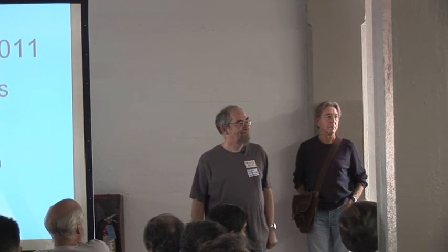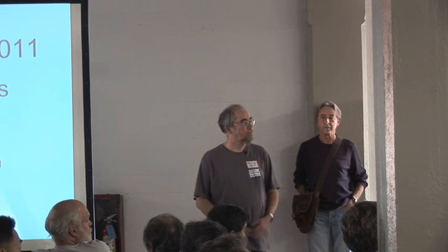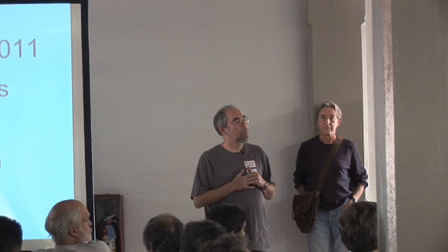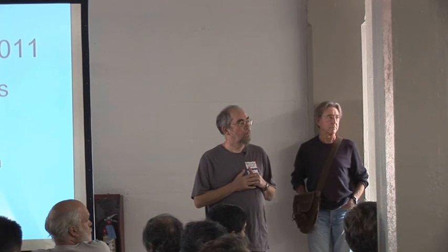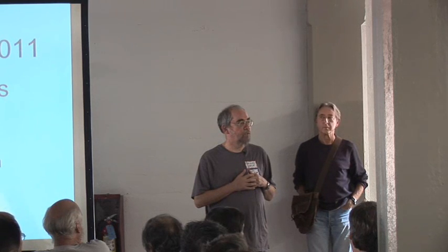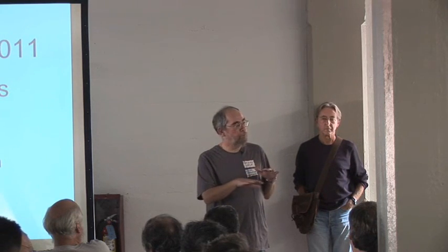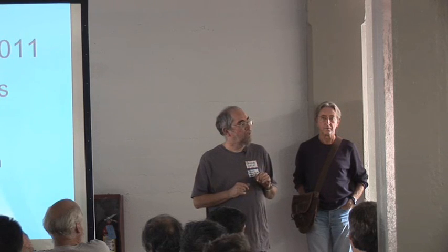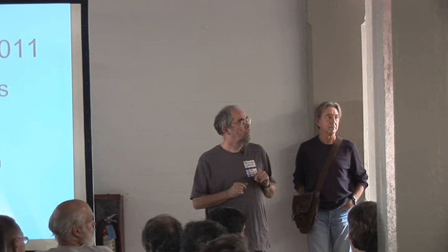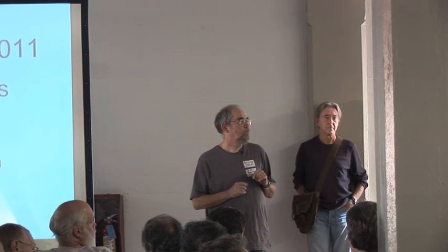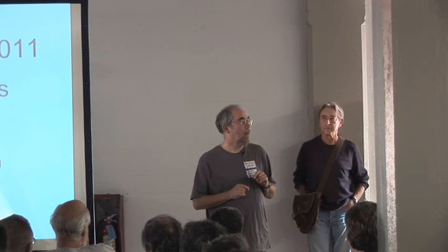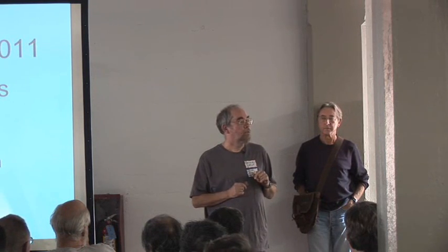However, have you thought of parallel inductors? Well, the amplifier is going offset, so what you do is you hope the thing doesn't burn up before the fuses go. Well, aren't you going to need a pretty hefty inductor to make sure that it doesn't load the feed to the mid-range? Because that's going to have to be probably an iron core inductor. It'll distort. Well, if it's a parallel, the distortion's really inconsequential. If it's a good low output impedance from the power amp, then yes, that should cope with that. It's a possible idea.